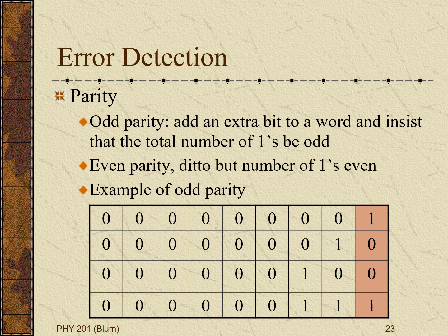So in that first row where there were 0 ones, you make the parity bit a 1. In the second and third row where there was 1 one, it was an odd number of ones already, so you make the parity bit 0. In the last one, when there are 2 ones in the data, you will make the parity bit a 1 to make it 3, to make it an odd number. And the purpose of this is for, as we say, error detection.